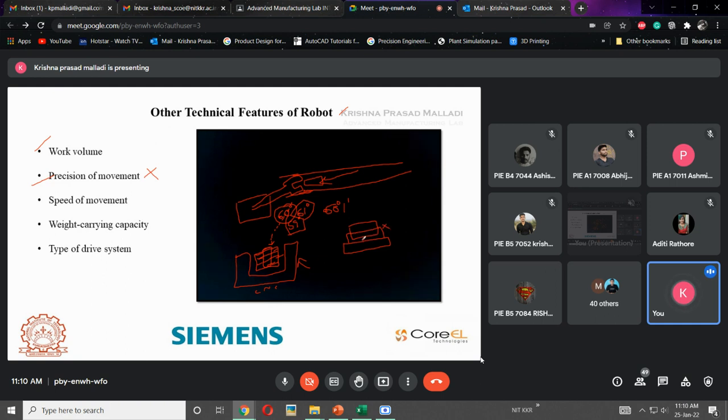It won't fit this cavity. Then what will happen? Again it will be a difficulty. Even with a 60 degree and 1 minute difference, the part will still be tilted in an upward or downward direction. It will be half in the cavity and half in the vice. It will be like this, so it won't fit. So precision in the movement always plays a key role.